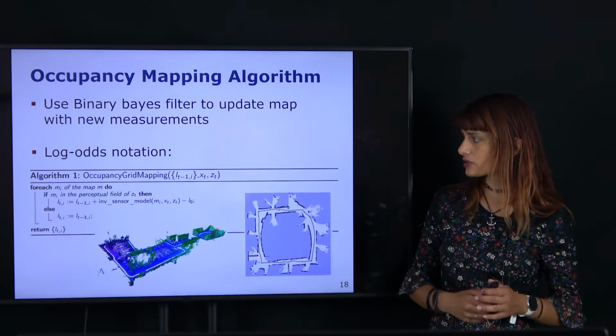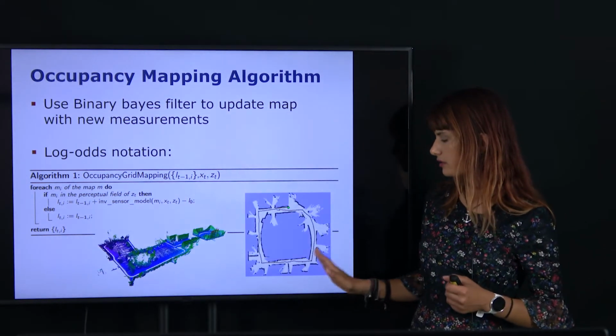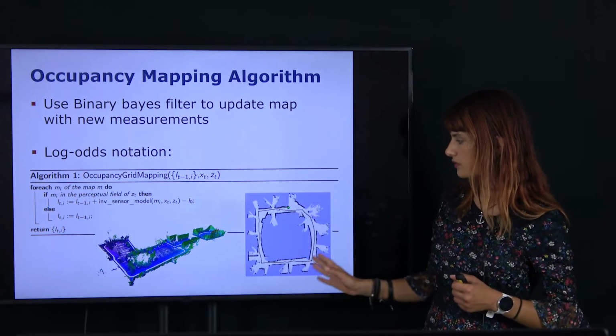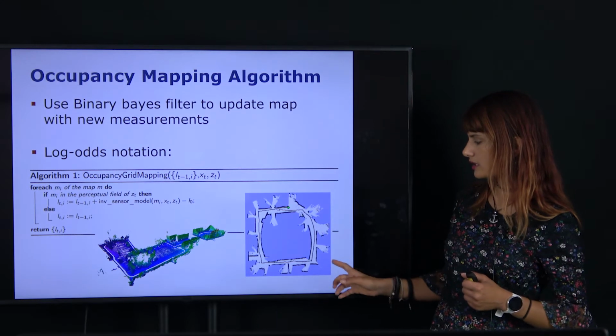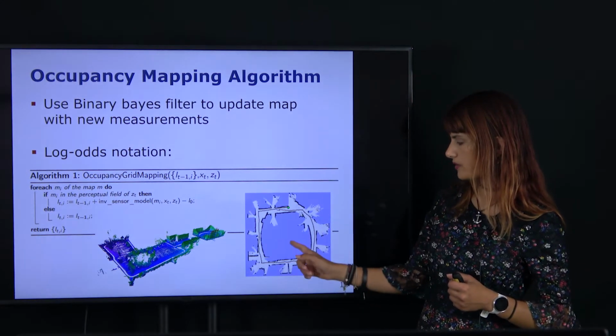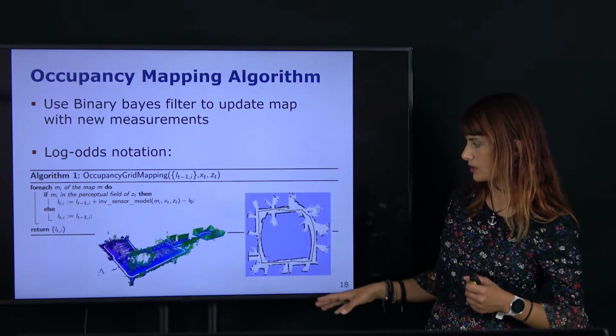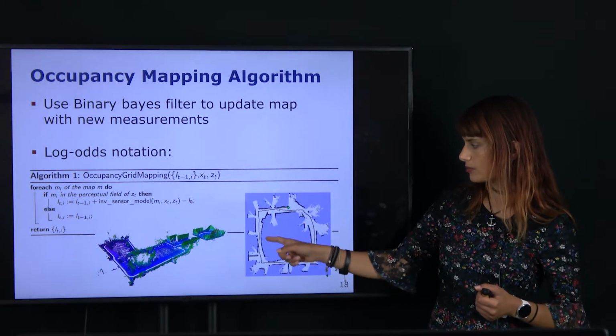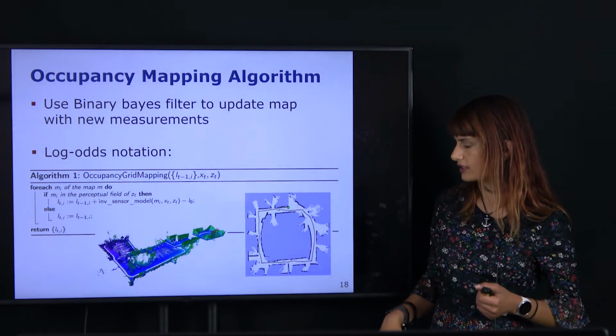Now, occupancy grids look something like this. In a two-dimensional environment, we have a robot that traveled a sort of loop around this large environment here. In the purplish areas, we see unknown areas that the robot has not seen, whereas the walls are in black and free space is in white.